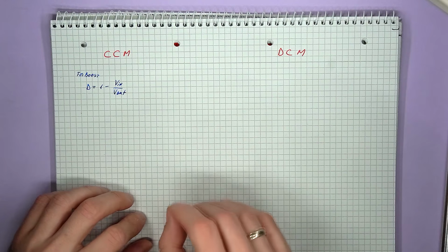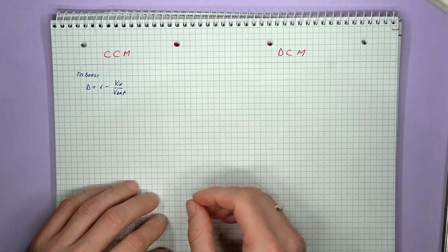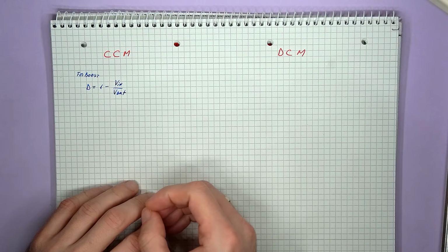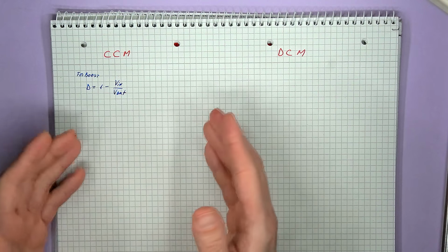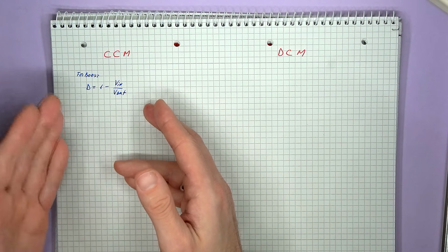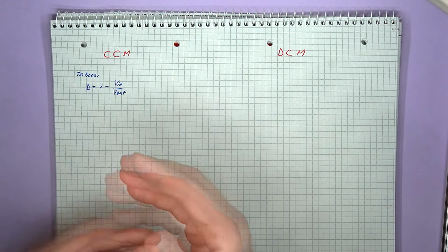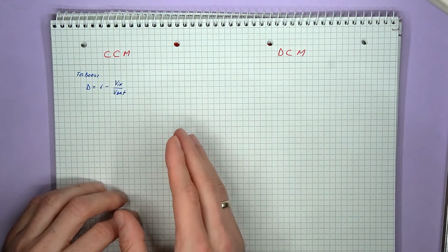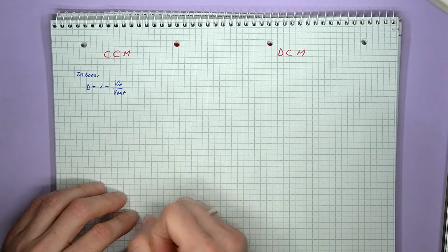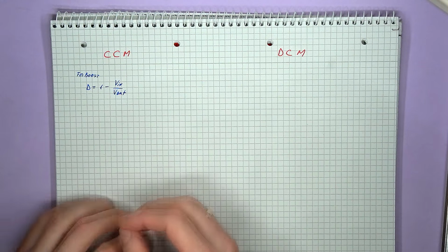If you had a choice, why would you go with one mode over another? One of the interesting things to discuss is how the output voltage is related to the duty cycle. So with continuous conduction mode, for most converters, you have some form of basic equation with the input and output voltage from which a duty cycle can be determined. This can of course be complicated a bit when you factor in various losses, but the point is that while the converter is kept in continuous conduction mode, the duty cycle is mainly dependent on the input and output voltage.